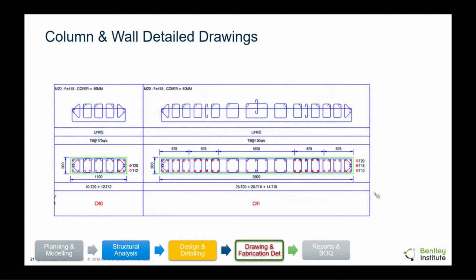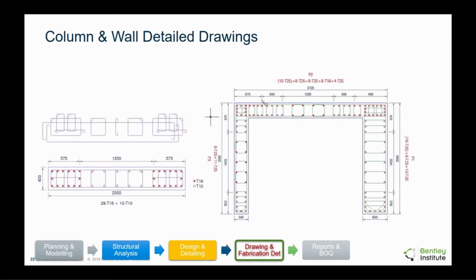Going further vertically, columns and walls, so we'll give you the cross section with reinforcement. Linking is provided, and you will get a copy of the links. So this basically tells the engineer or the guy on the site, how is this link set actually compiled? So I have a master link, I have a second set of link, I have a third set of links. So how is the link set actually compiled? So it actually gives you all that information within the drawing.